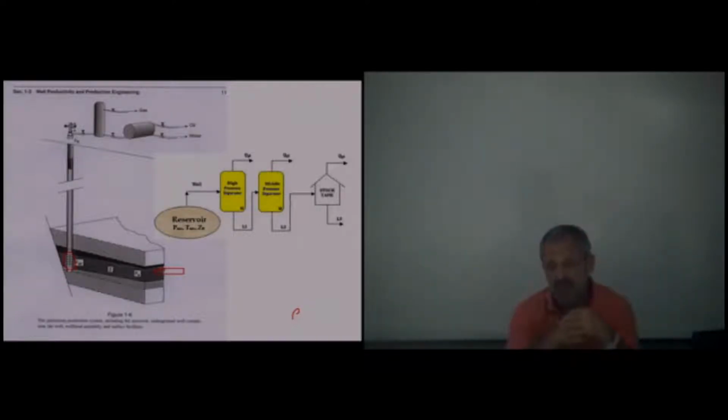But it's not just water, because typically we have to weight up the water so it equals the bottom hole pressure of the formation we're drilling through, based on its fluid gradient. If it's less than the pressure of the formation, we have a kick, which could be a blowout.